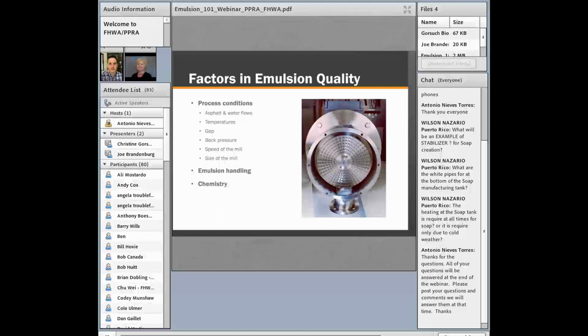And what's happening is that you have small little soap pockets inside of the mill head, turning into steam, so the back pressure is spiking, and what that'll do is give you an uneven particle size distribution. So that's one thing to keep in mind. Make sure that your mill is being properly fed, and that the asphalt and the water flows or soap flows really are consistent.